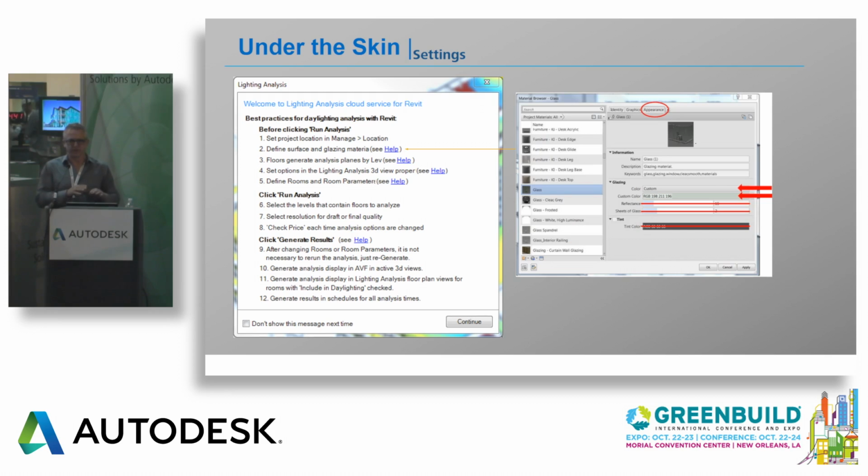transparency. The opaque materials are generally pretty good. The default materials that we use in Revit are pretty good. Everything else is pretty much what you see is what you get. Really, the way the tool interprets materials is generally a little bit better than what people would judge to be the reflectivity of a surface. So it's best to go with the opaque materials defaults.